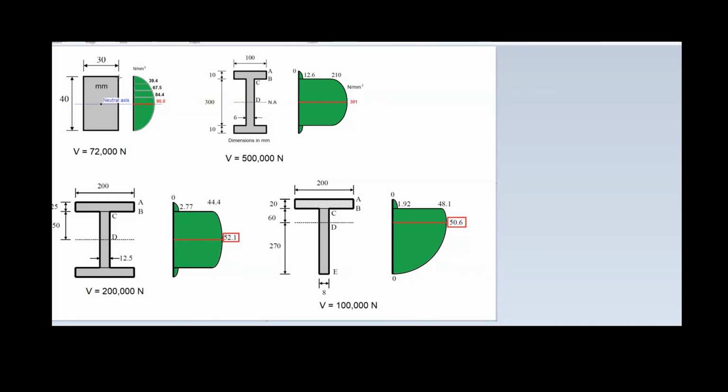the width of the cross section, is constant along the whole height of the cross section. This is the reason why this is so nice and this shape is uniform and continuous, because there is no change other than the distances and the areas you consider for the different points to evaluate the shear stresses. The units are always in Newton per square millimeter.